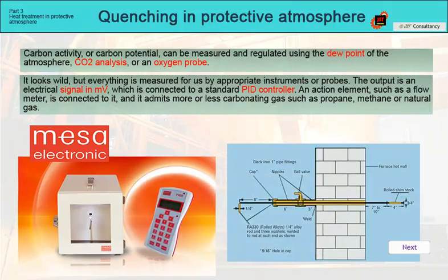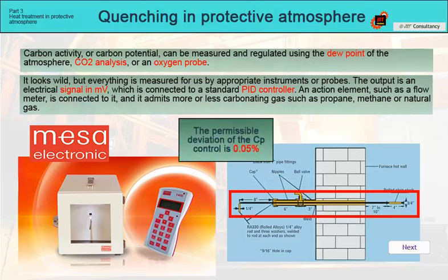This data then corresponds to the CP in the furnace. The condition for its use, however, is that the furnace has a hole for inserting the holder with the foil. Inserting the foil is not entirely simple either, and requires not only equipment, but also experience. If an oxygen probe is verified in this way, then the foil test should also be carried out near it so as to best express the potential of the probe. Therefore, for the furnace to comply with recognized standards such as CQI-9, the carbon potential control must be able to maintain this parameter with a deviation of 0.05%.